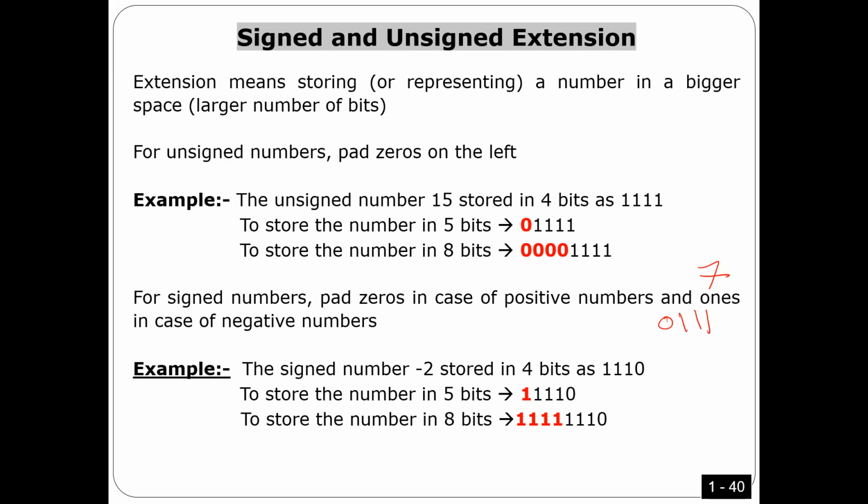If I give you a signed number and you want to know if this number is positive or negative, yes, this is something you can guess from the number. Just look at the most significant bit. But signed or unsigned, this is not something you can guess. So this is something you have to consider when you design your hardware. There should be a hardware circuit for both signed numbers and unsigned numbers, okay?